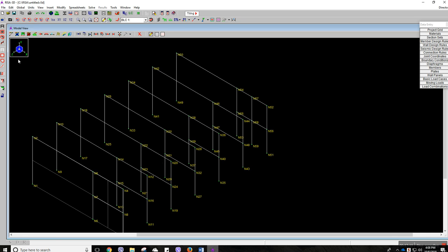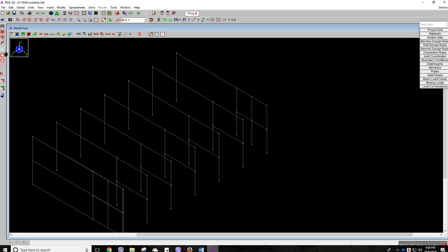There is one nice feature in Risa 3D. What you can do is, there are icons here. These 4 white icons are to deselect. You can just put your cursor there, and it will tell you how to do that. And these 4 icons in black are to select the members. So this is going to unselect all the structure that you have drawn. Just click on that one. And there is another easy way, you can just click on one member to select and deselect again.